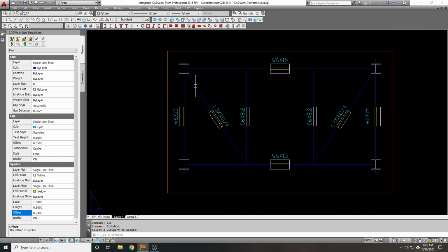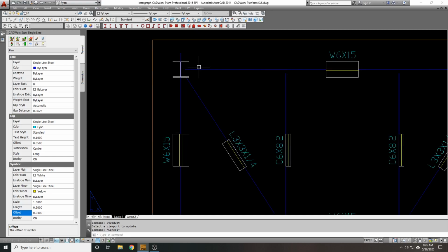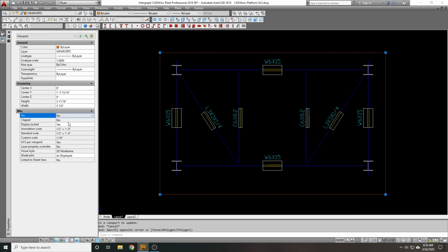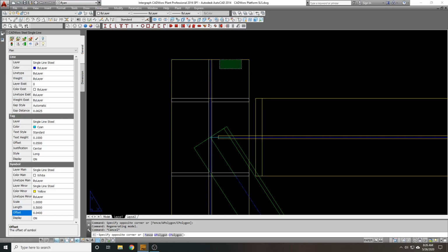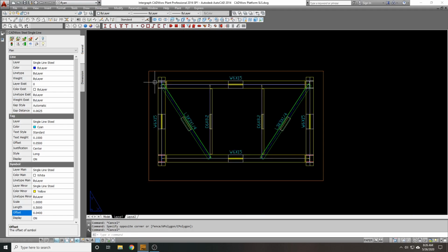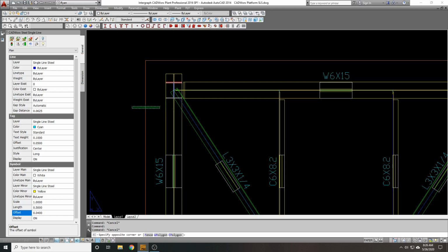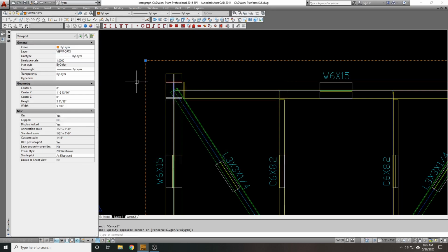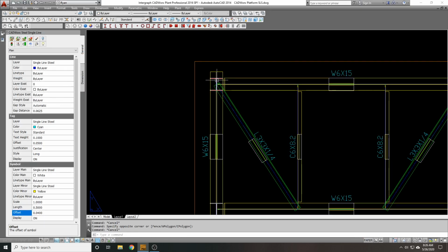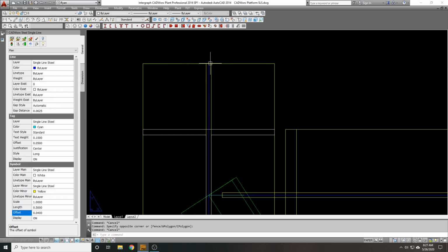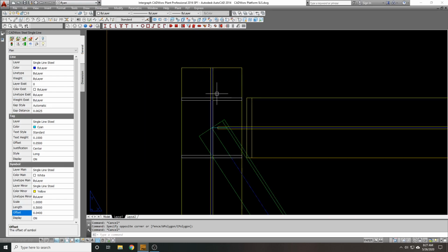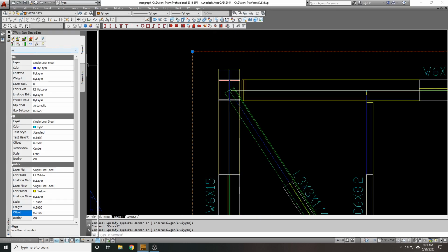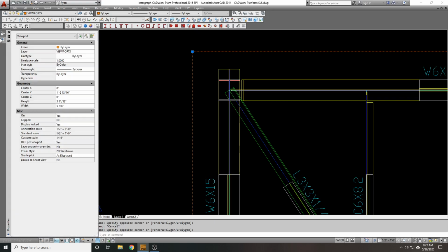Okay, now we have these gap distances I was talking about. You can see the gaps have already been created automatically. That's awesome. However, you'll notice that when I turn this viewport on, oh no, these actually already went all the way, which is fantastic. That's one of the benefits of using the automatic gap tool, is that it knows that this is the end of the beam and there's nothing over here, so it will make it go all the way. And that's hard to understand without seeing. It's not like I'm just talking nonsense, but let me show you what I mean by that.